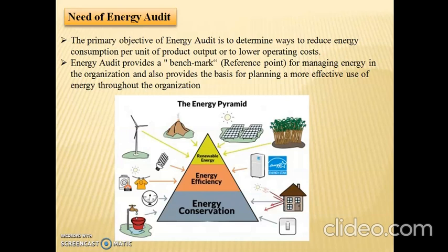Likewise, how much energy is required to produce that particular product, that benchmark you can set after conducting a detailed energy audit. This benchmark also helps you compare your energy consumption with an industry which is producing the same product.